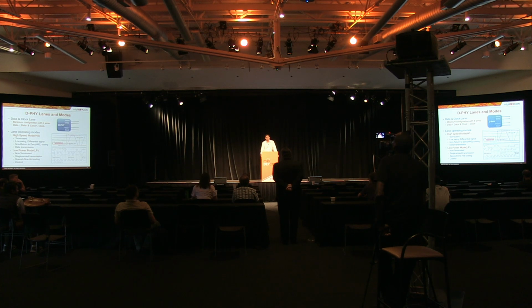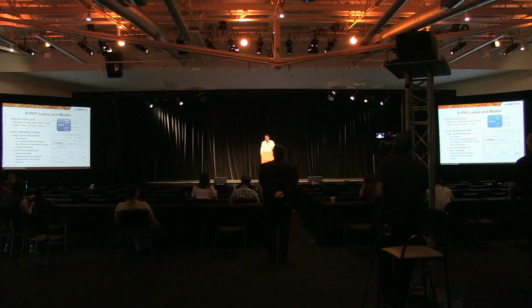Yes, I think in general, I would say yes. But I've heard concerns that this particular interference test, people are not able to do it very well. If you go back a few years in D-PHY, there was always a challenge, very difficult to add these kinds of stresses, whatever we just talked about, the E-spike. It was difficult, challenging, adding different boxes together. So people had generally covered the CTS, but there would be one or two here and there which they would have to struggle with.